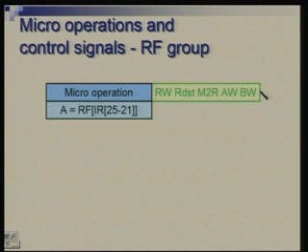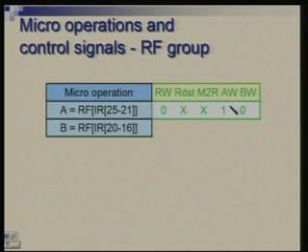So, reading RS into A, we make RW 0, RDST do not care, M2R do not care. These RDST and M2R will be relevant only when RW is 1. So, when you are reading, these do not matter. We give a write signal to A, and B does not require. Similarly, reading into B is similar, except that we make BW as 1.